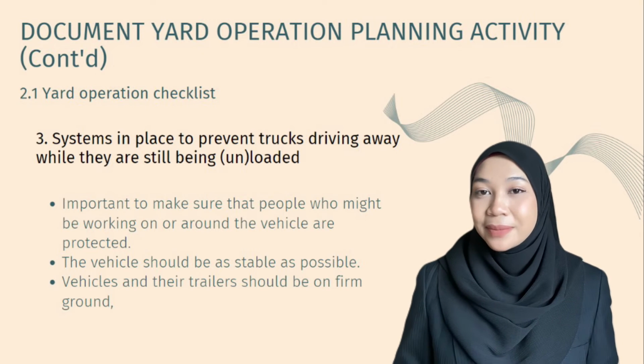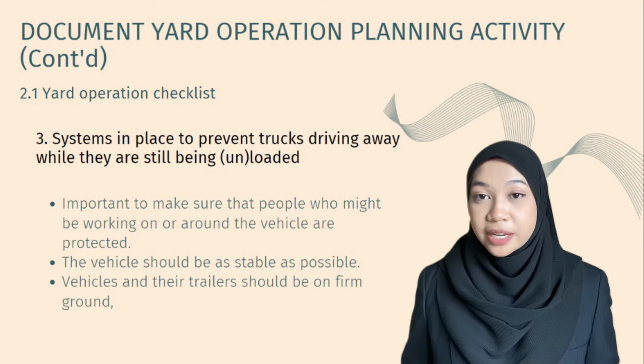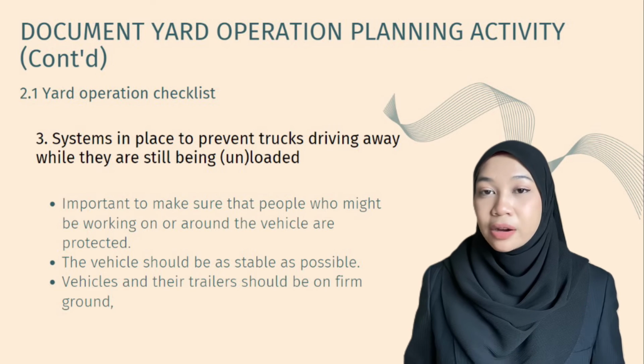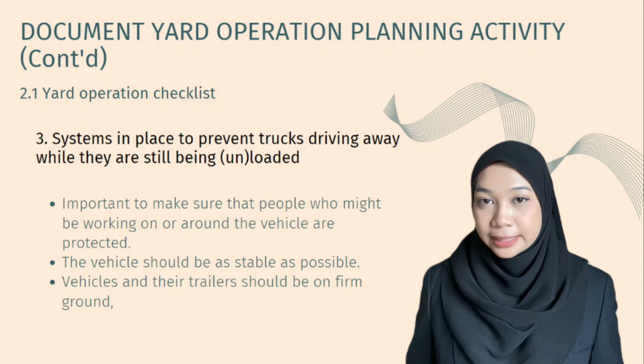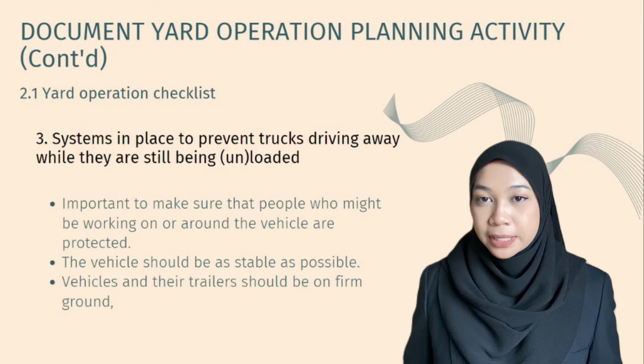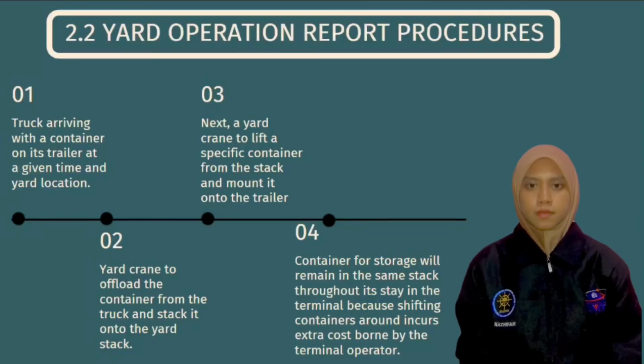Next, a system in place to prevent trucks driving away while they are still being unloaded. It is very important to make sure that the people who might be working on or around the vehicle are protected. The vehicle should be as stable as possible and their trailer should be on firm ground.